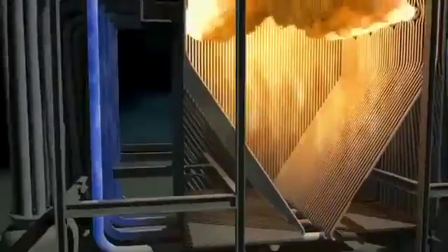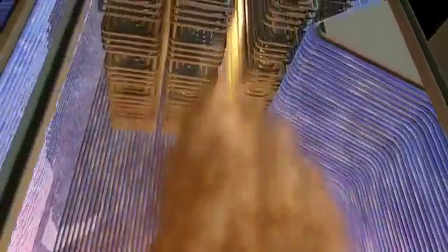Liquid water flows through large tank downcomers and into the base of the firebox. A network of 2-inch tubes line the firebox walls, and burners force feed a continuous supply of combustible fuel into the ultra-hot firebox. Eventually, the insides of the firebox burn so hot that its surrounding steel walls would melt if not for the tube-lined walls of liquid water.